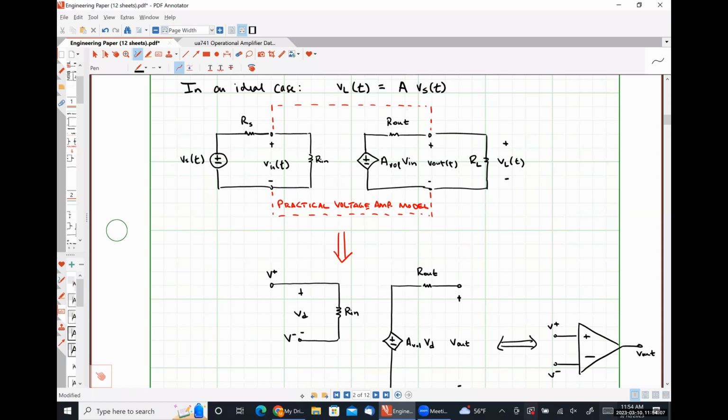So this Vs of t is measured. So this is the positive polarity terminal of Vs of t, and this is the negative polarity terminal of Vs of t, right? And we could just as easily say that this is ground, so that this is measured with respect to ground as well, because we know that this output is just a scaled version of the input. So it should have the same ground reference on either side of the representation. All we're doing is we're no longer forcing the negative polarity terminal here to be at ground so that we can have a differential input signal.